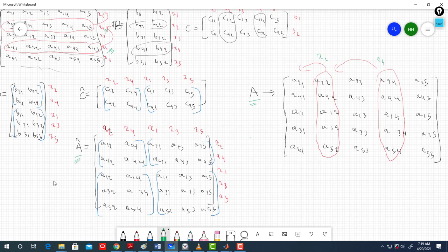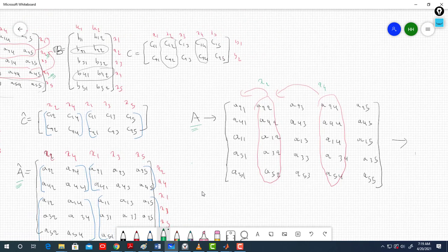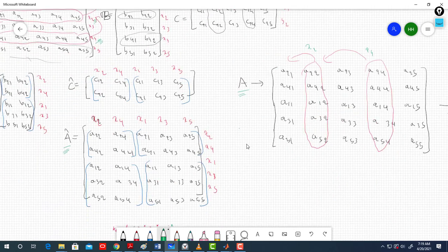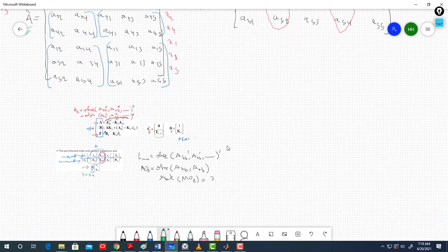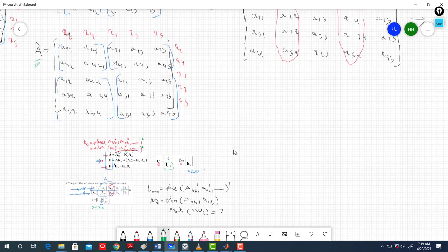That's what I did in MATLAB to find my matrices. I find my matrices, I demonstrate the minimum order observability, so it is a rank of 3, right? Once I'm done, I do it in Simulink.